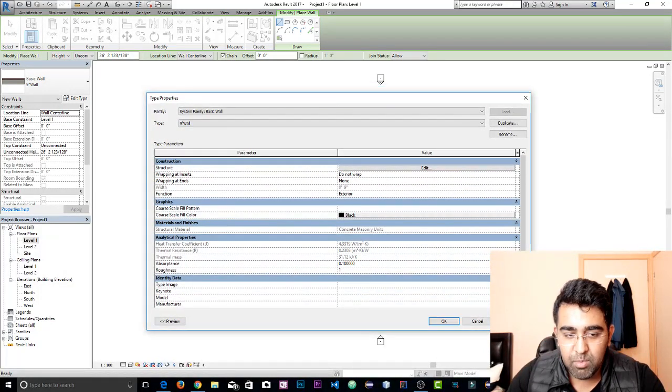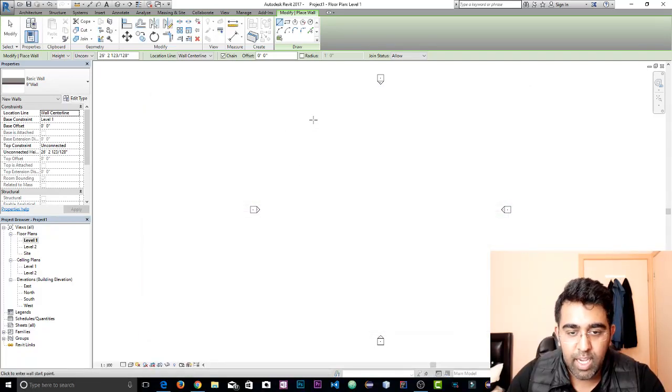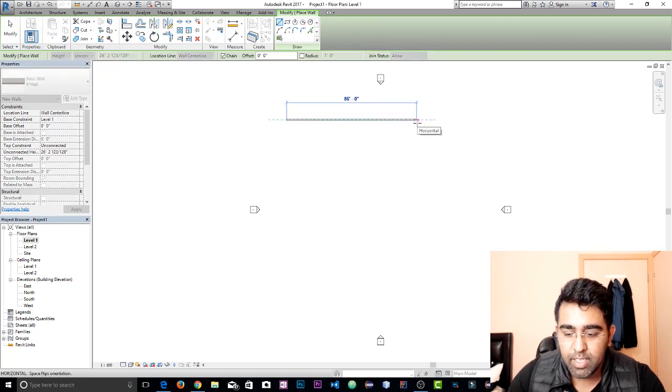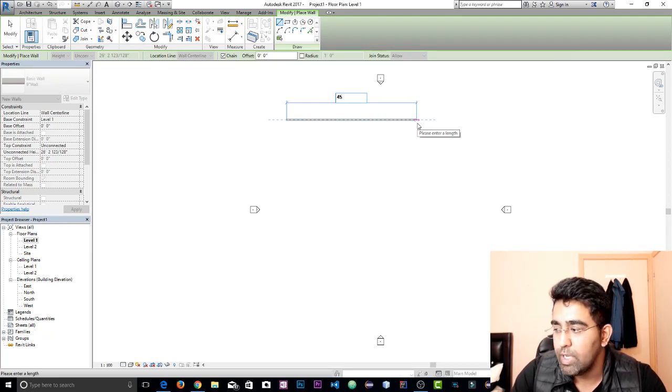Okay, let's click on apply. We got structure done. Now, because this is my dad's project, I will start from here. I'm gonna take my cursor here and we'll type about 45 feet. I'll type 45. I don't have to type the quotation mark because the first value is always feet, and if you give it a space here and type the second value, Revit would automatically detect it as inches.